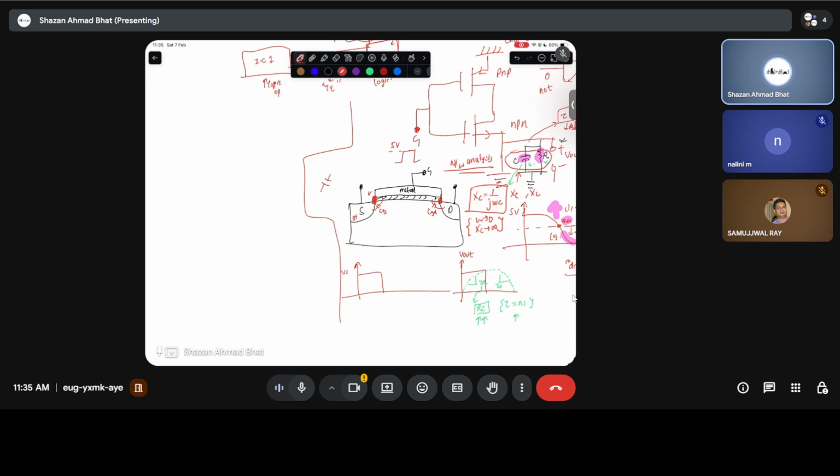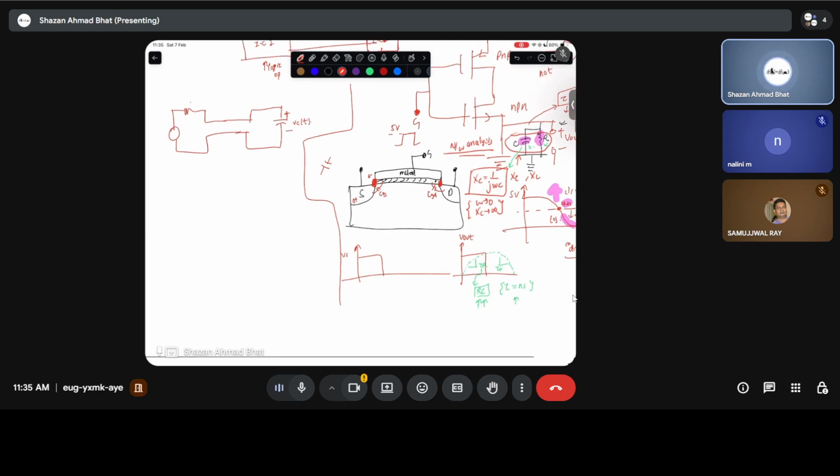So now, if you for example have a voltage source which is connected to, let's say, a resistance, and then you have a transmission line connected to it, and it's ended at a load which is capacitive in nature, and this is the voltage across the capacitor. Okay, you know that any voltage given to it will rise with a certain time constant, which is given by the RC time constant. That's what I was basically discussing in the case of a transistor, because there will be intrinsic resistance associated with it. So this will be R, this will be C.